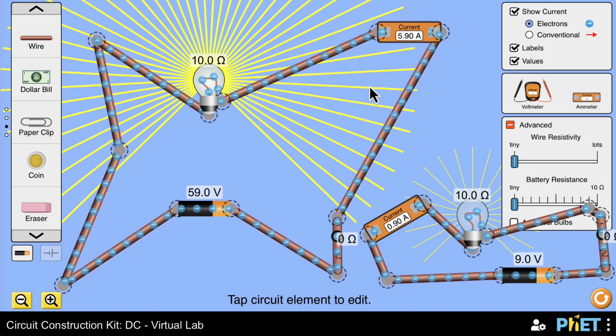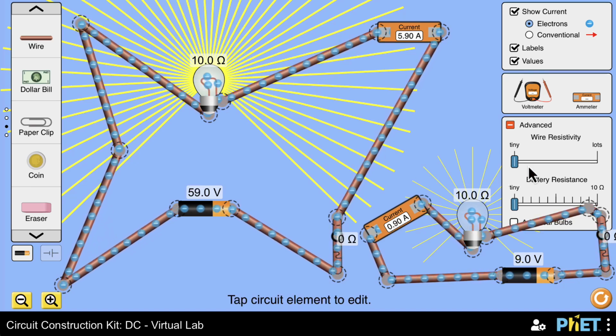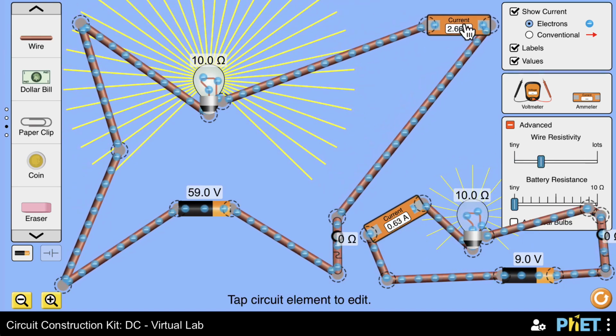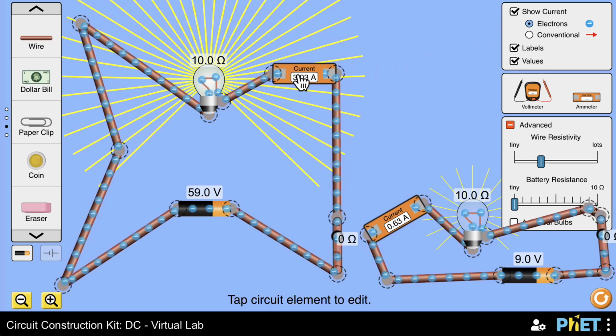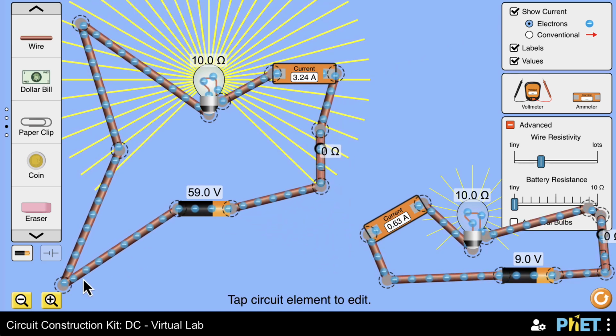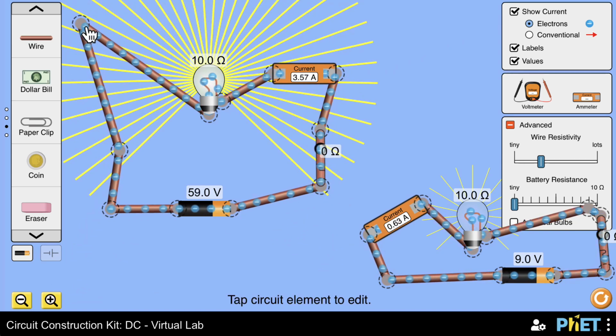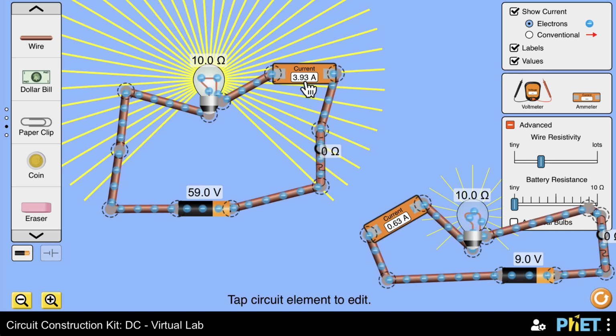But in real life, if you're having a science project and you're trying to build a circuit, don't use long wires in your circuit. Something else affecting the resistance of wires is their thickness, but this is again a topic for another time. Right now, what I want you to know is, when you have longer wires in real life, you have more resistance. Longer wires, more resistance. Shorter ones, less distance for electricity to go, so less resistance and therefore more current.